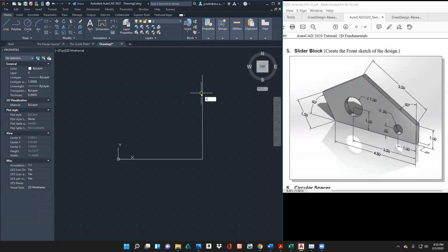I'm going to type in rotate, R-O-T-A-T-E. Reading the command line, it says select the object, enter. The base point is at that endpoint right here. And so the angle is going to be, I always mess this up. Let's type in minus 60 and see what happens. I think that's it. Nope, I want to go the other way. So type in rotate, select the object, push enter, select the base point, which is right here, and type in 60, which goes counterclockwise, all right?